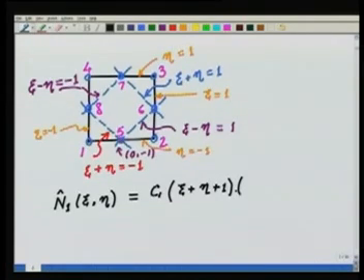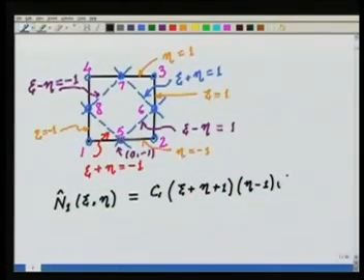What about the next one? It should vanish now. Here it has taken care of these points. Now this line and this line. This equation is eta minus 1, and this line is psi minus 1. So you see that by this choice of these products, I will get this function vanishing at all other points in the element.